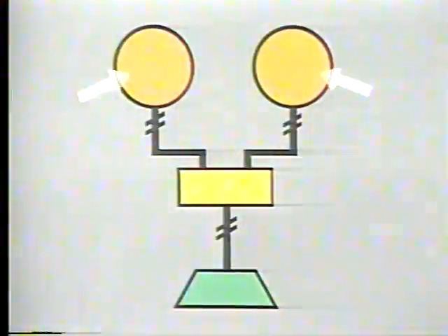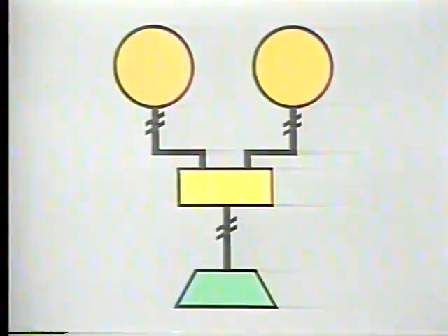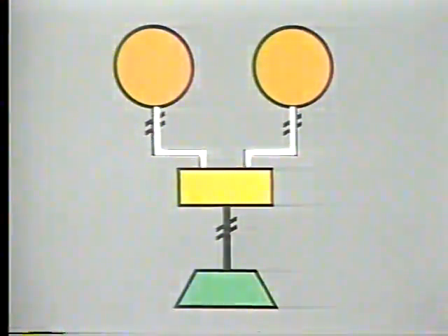In this system, there are two measuring elements, a controlling element and a final controlling element. Each of the measuring elements monitors a process variable, and each provides a signal that represents the value of the monitored variable to the controlling element. In auctioneering control, the controlling element responds to only one of these signals. For example, the controlling element may respond to the higher or lower of the two signals. This symbol tells us that the controlling element responds to the higher of the two monitored variables.